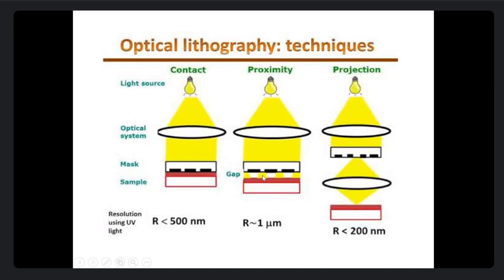Anyway, another option left in our hand, and the much more attractive solution that you can go for, is basically the reduction of the wavelength of the light source. That means here we are trying to replace this light source with one that has a lower wavelength, that means higher frequency. That is why people basically moved from UV to deep UV. Deep UV means, as you can understand, lambda is smaller and frequency is higher.